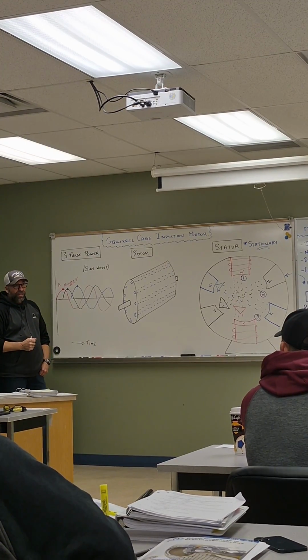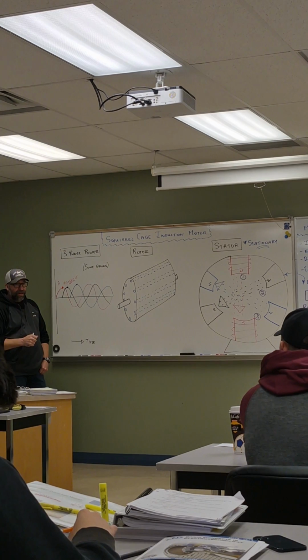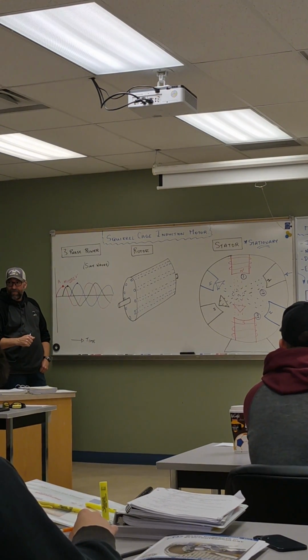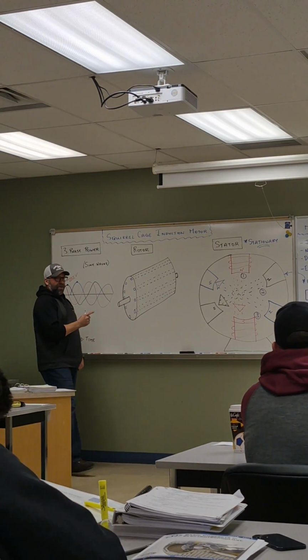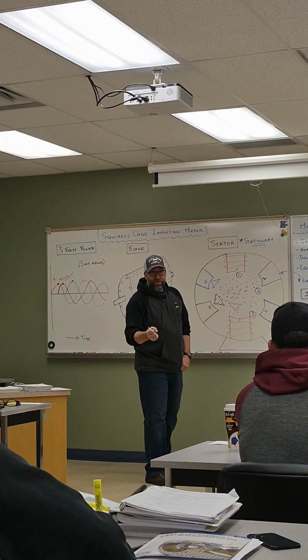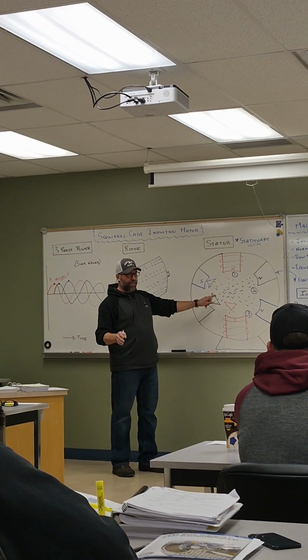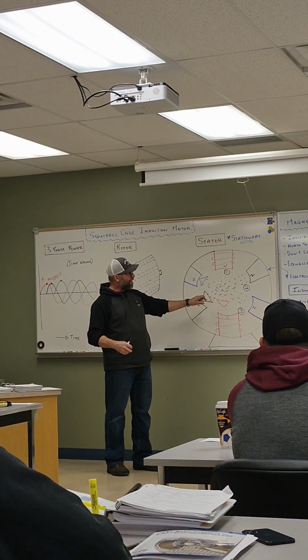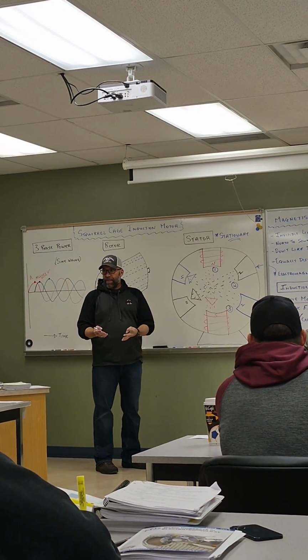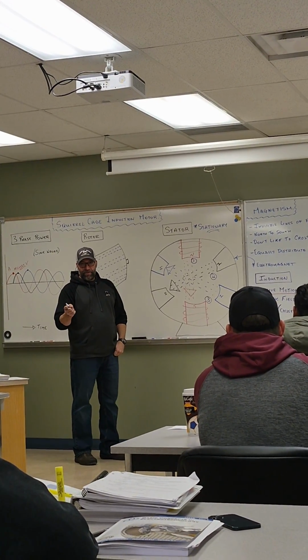Clearly, what I have going on is a magnetic field that forms, collapses, and then another one forms and collapses, and then another one forms and collapses. The phenomenon, Lenz's law and Lorentz force, is this: even though it looks like it's on, off, on, off, on, off, in total, how it reacts is a rotating magnetic field.